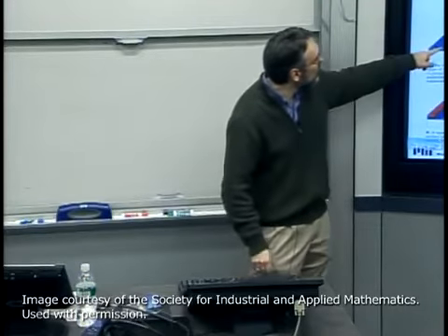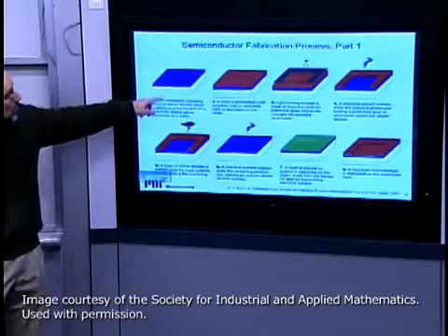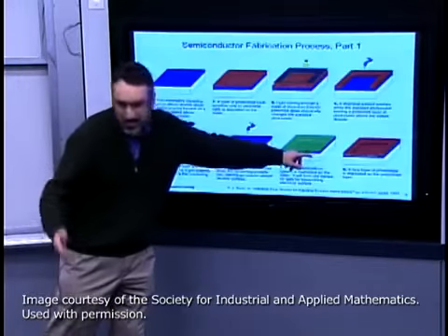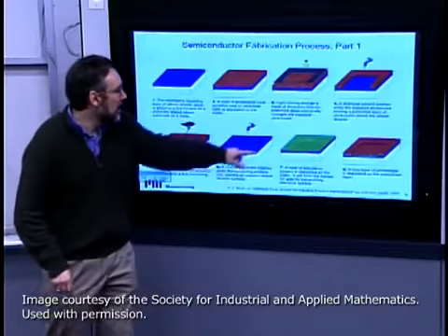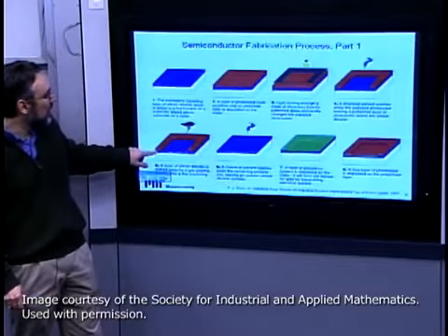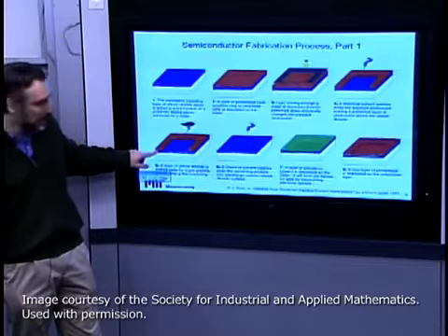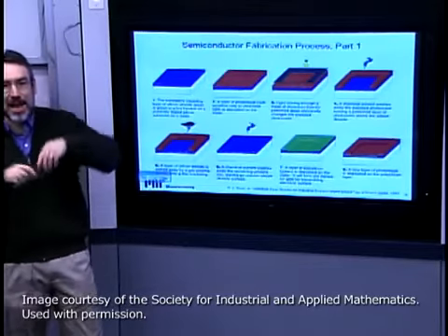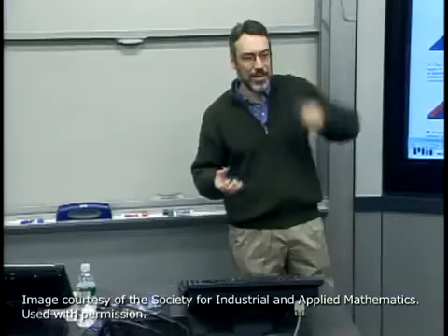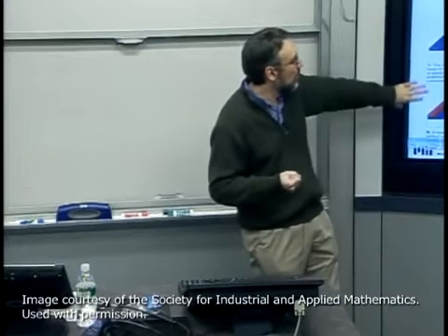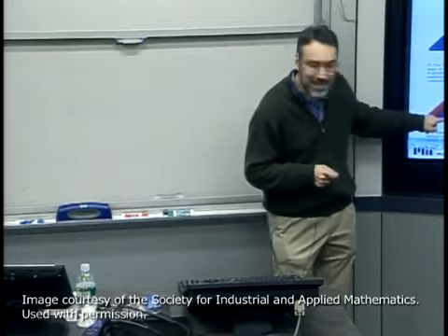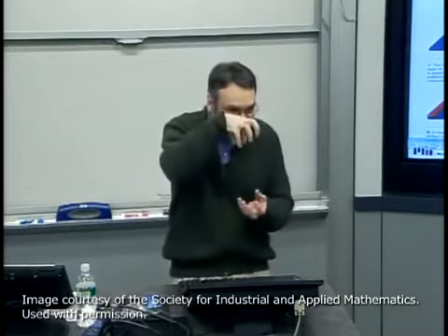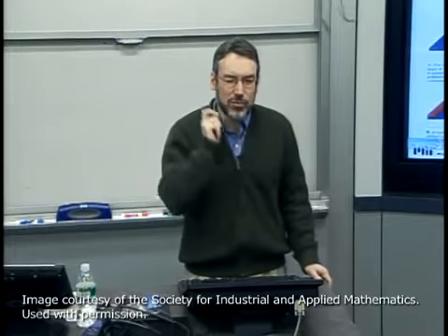So typically, what you might have, close to modern technology, is half a micron of silicon dioxide, fairly thick silicon dioxide out here, to act as a very, very big insulating layer separating your metal electrodes from other components. But this silicon dioxide layer that's used between the gate and the semiconductor needs to be extremely thin.